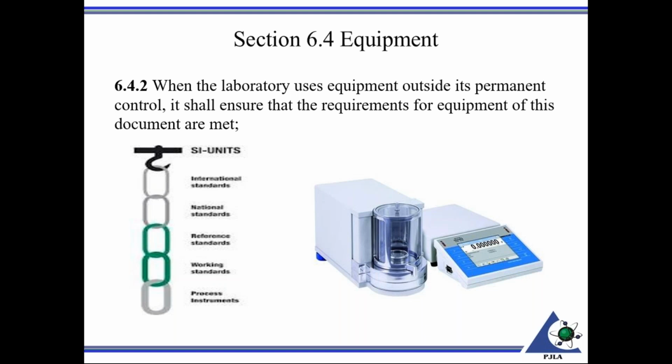Those of you that send equipment off, perhaps to be calibrated, if you think about it, the equipment is shipped to the calibration facility. They do the calibration, provide you a nice report, and then it's shipped back. So in the interim there, technically it's out of your control. So it's a good idea, like I said, prior to shipping out, to have an intermediate check. Just check it when it goes out, check it when it comes back, see if there's any deviation there that could be detected.